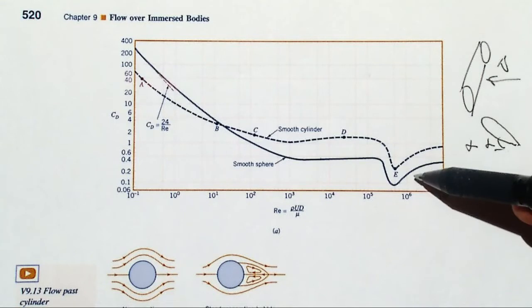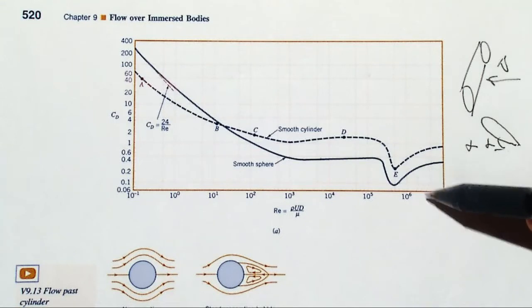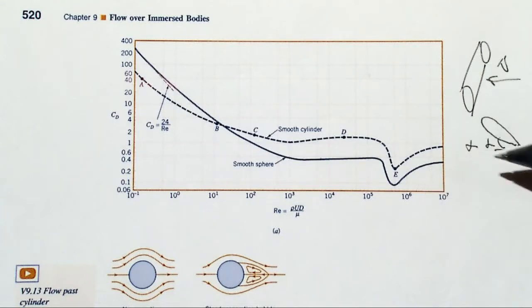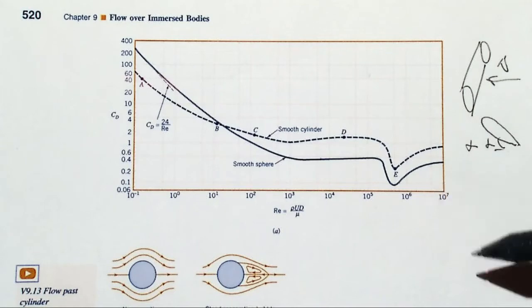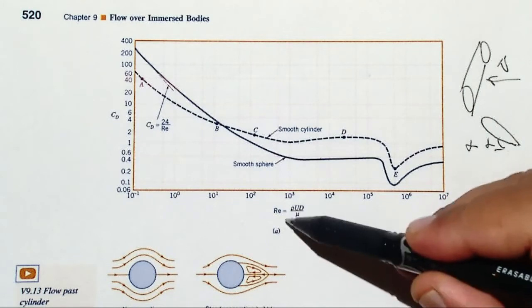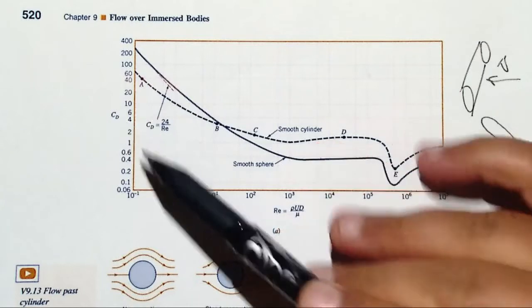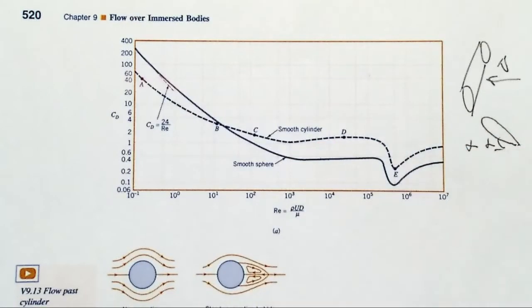So that could be a plot in 3D, because you have to know the angle of attack. So you have the Reynolds number, you will find the drag, but based on only one alpha. When alpha changes, this is going to give you a different drag coefficient, so this plot is going to change, right?